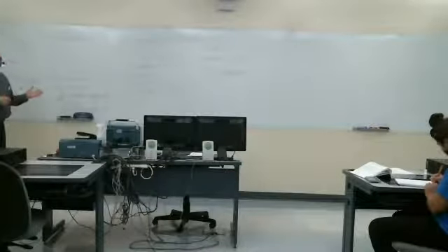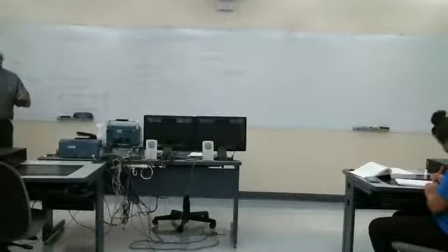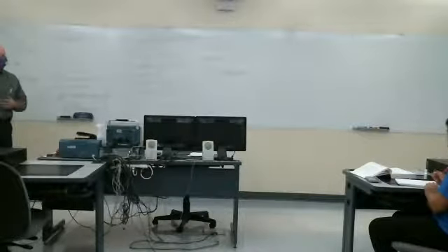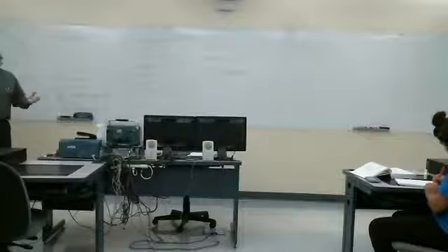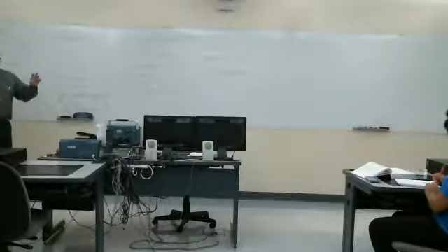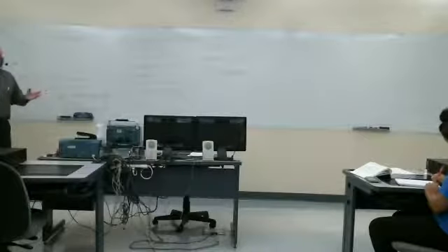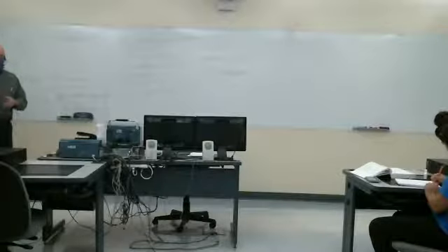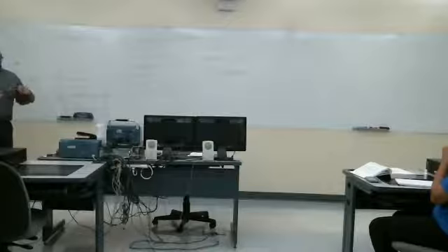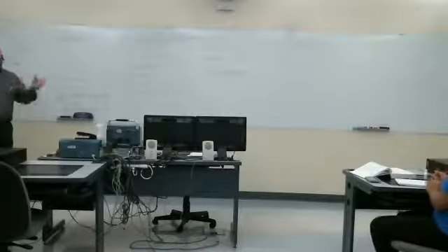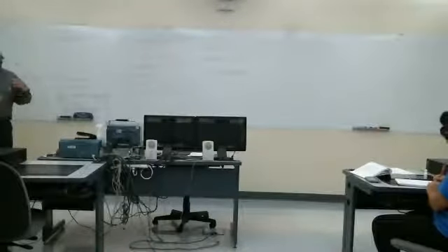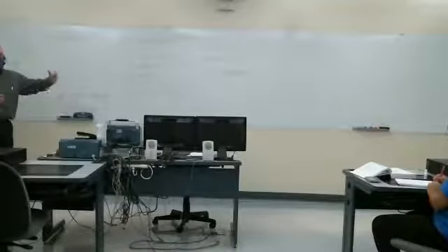What it says from a circuit standpoint is, if I come in here and hook up a function generator at a certain amplitude, at a certain frequency, or I switch on my DC supply, and I measure the output of my circuit, and I get some output, time invariant says if I come in next week and do that same experiment, same function generator settings or same DC supply settings, I should get the exact same output.